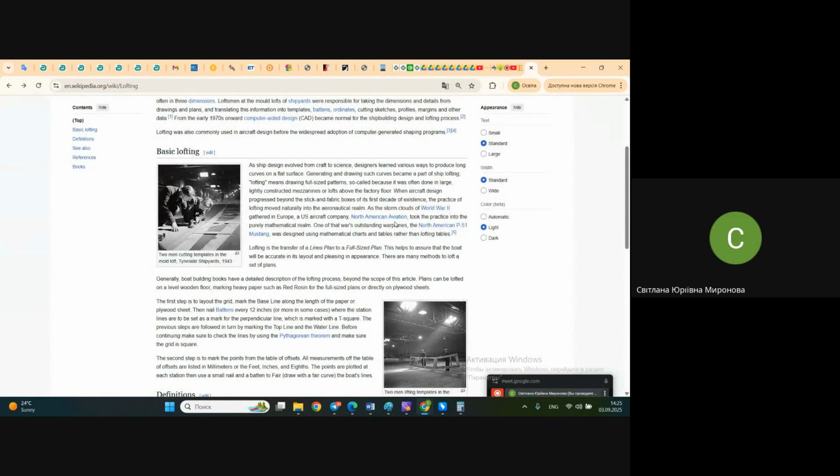Well, next, by these templates they produce tooling, copying from templates. After tooling they produce parts, and next assembly tooling, which is also independently produced, meets with parts produced on other manufacturing tooling, and everything should coincide, everything should give the final contours, outlines of the airplane.